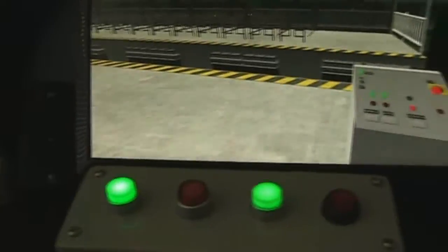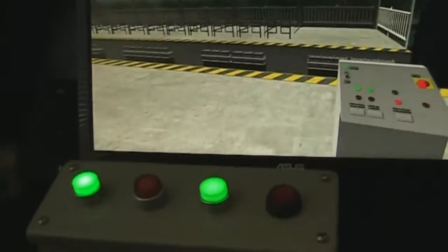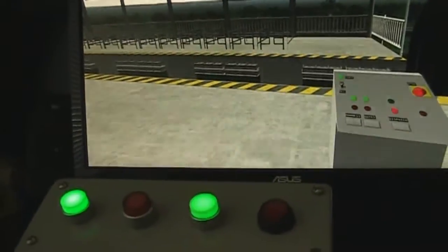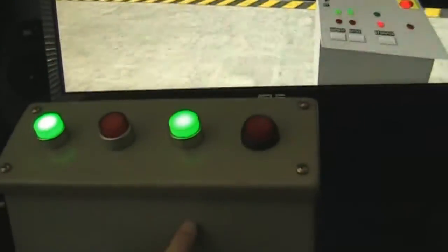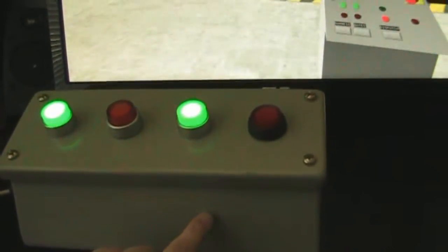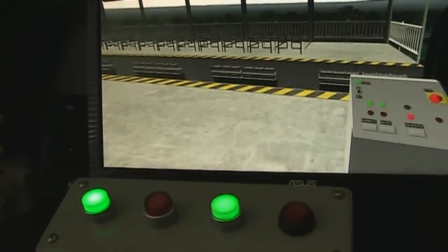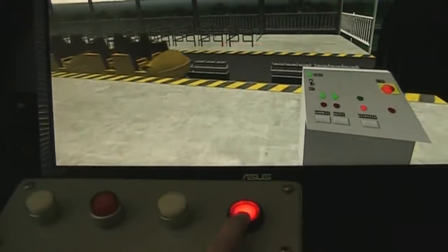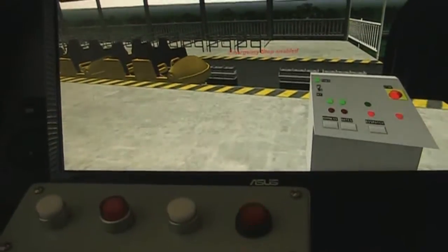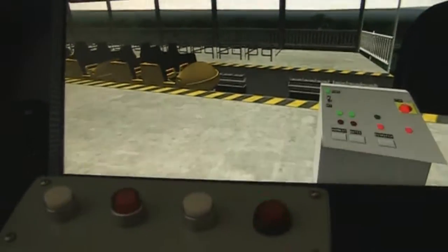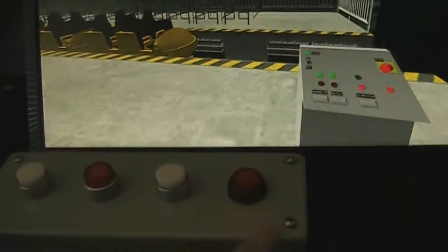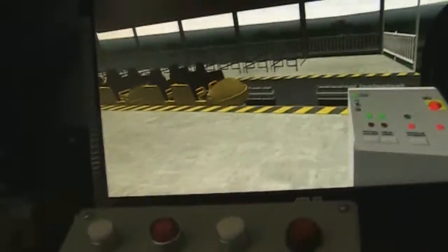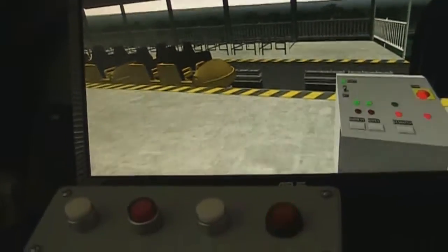And as soon as the next train's coming in the station, I'll push the red button here to show you what the e-stop does. There's also a piezo speaker element inside the control panel here on the breadboard, and that will basically create a warning sound that I programmed in when you hit the e-stop. So you see, when I push the button, the red light flashes, there's an annoying beeping sound to signify an e-stop, and of course the train is stopped in the station.